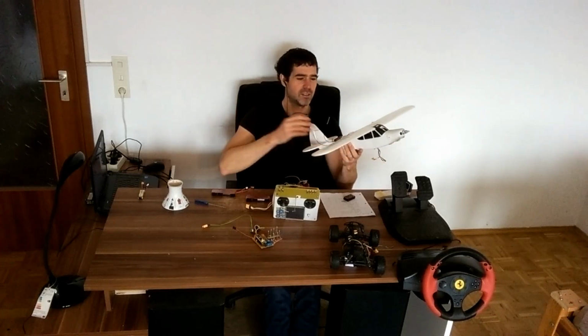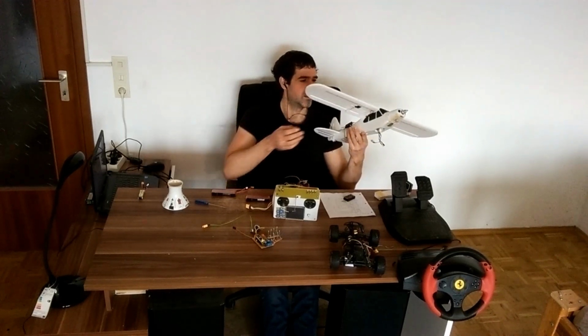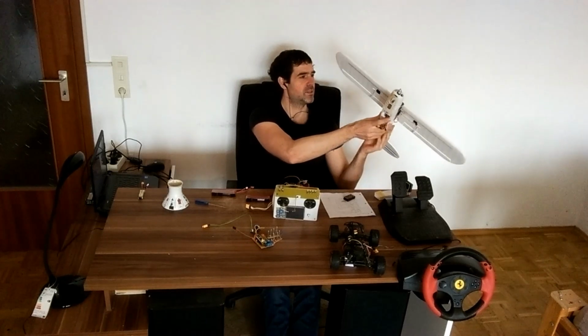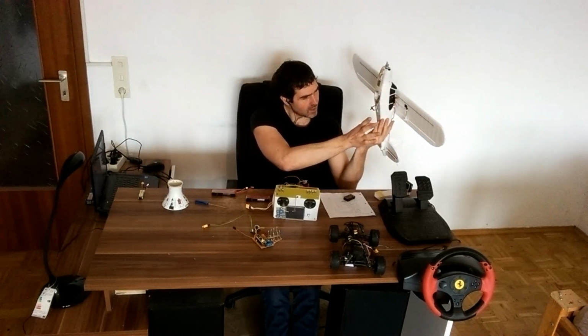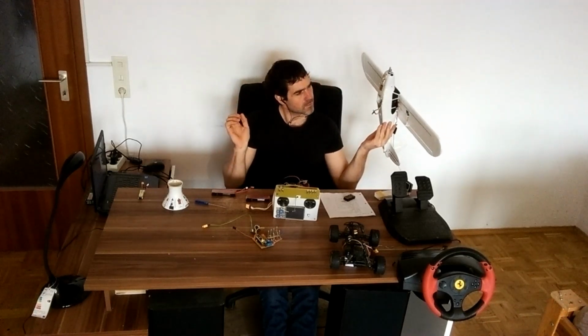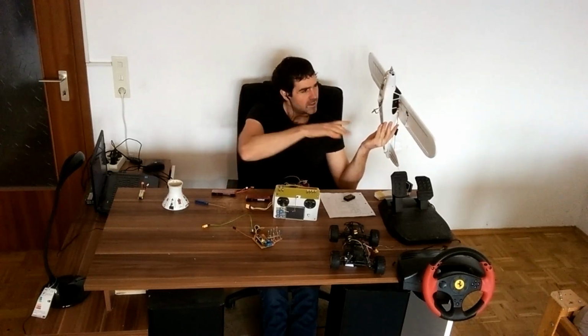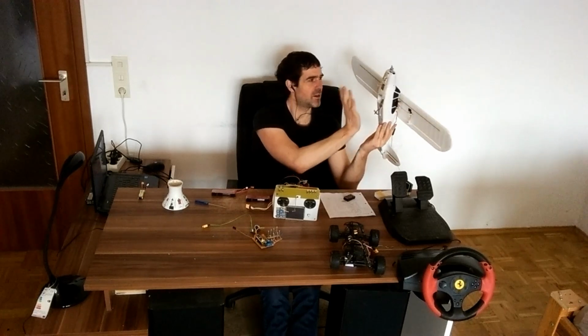It's an artificial name, artificial wording for describing putting together the function of ailerons and flaps. On this small plane, for example, there are ailerons, and each aileron has its own servo. One thing to notice to understand what's coming up is that the servos, the way they are mounted in the wings, are mirrored to each other.